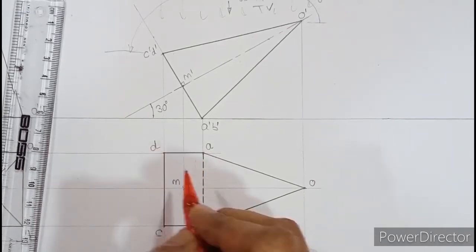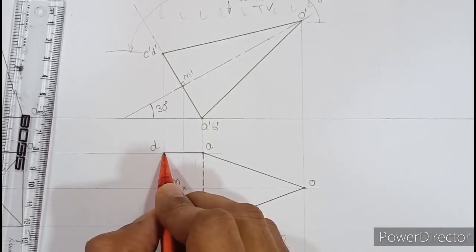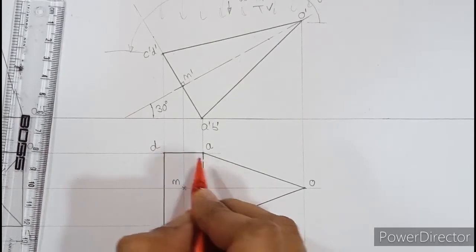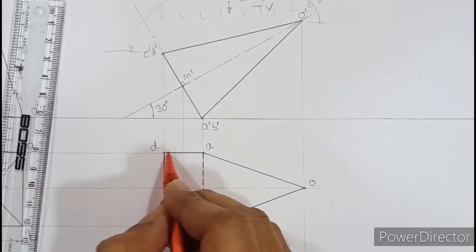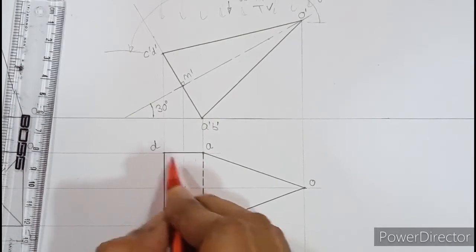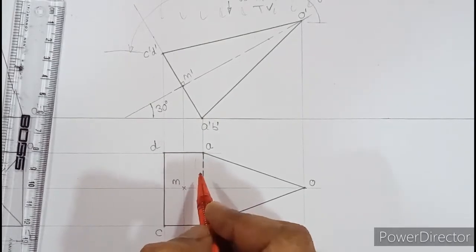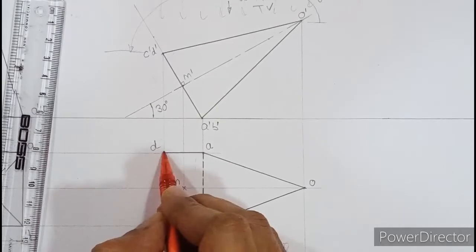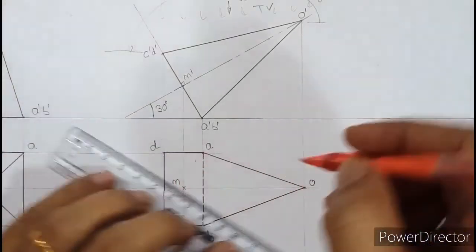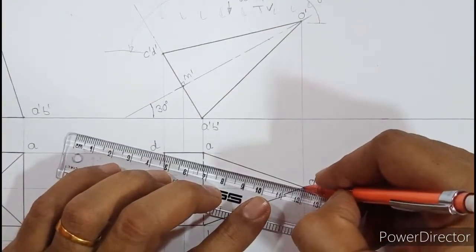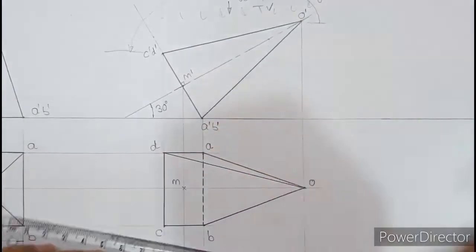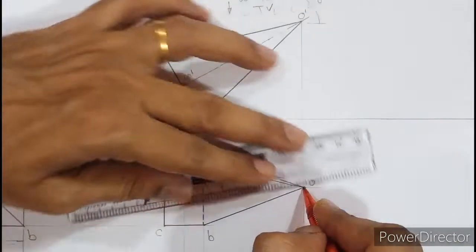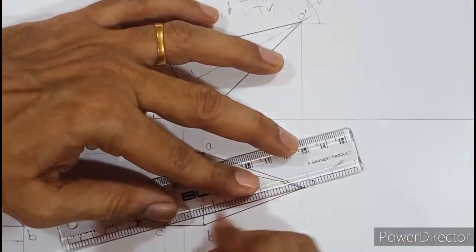So see, D is a dark corner, and from a dark corner you should draw a dark slant edge. Suppose AD and CD were dotted, which is not possible. If D was a dotted corner, then you should draw a dotted slant edge. And what is a slant edge? A slant edge is a line joining the base corner with the apex. So because D is a dark corner, draw a dark slant edge OD. See, this was very difficult to visualize. You can see one more triangle in the side also. And from here you should join O with C, because C is also a dark corner.